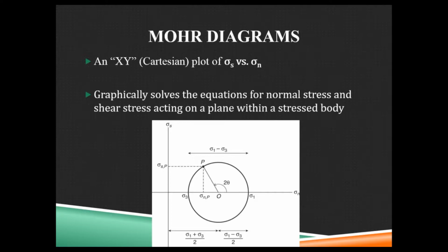There's zero shear stress. And so this diagram doesn't have numbers, but supposing sigma 1 was 4 and sigma 3 was 1. So you'd go along the sigma n axis, put a dot at 4 and a dot at 1, and that's the start,